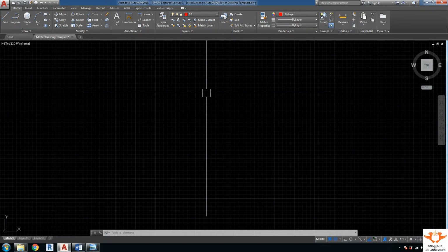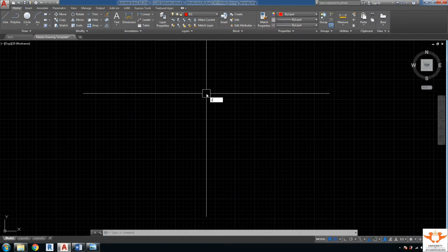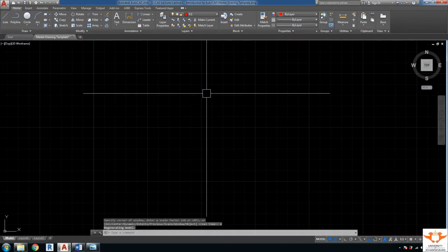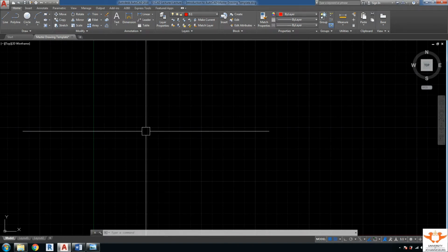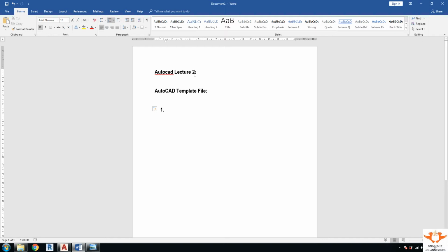So the first thing that I would like all students to do is type in the shortcuts Z, enter, E, enter. Okay, so students, this is a shortcut to allow AutoCAD to zoom into a relatively normal scale so that we could draw a line, and the line shows in full on the AutoCAD model space. So I'm going to just type this in for you guys.